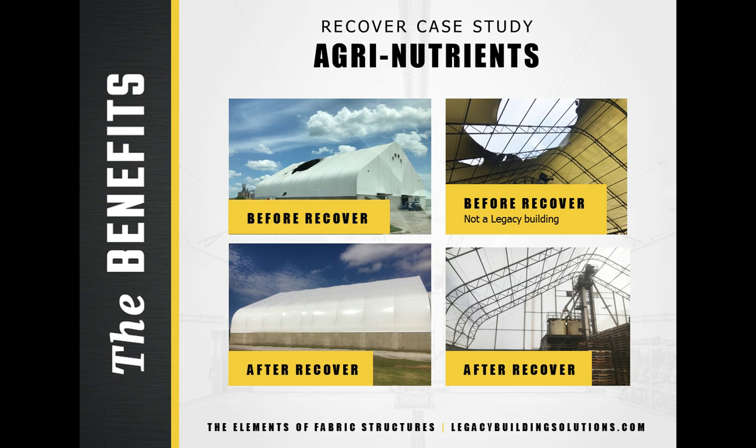As shown in the picture above, a fabric building is self-ventilating. In the presence of heat or fire, the PVC will melt away from the flame rather than feeding it. Often, most of the damage from a fire is caused by excessive heat buildup within the building. In a fire event, the fabric melts away, allowing the heat to escape and drastically reducing the damage to the building. The ventilation also provides an escape route for smoke, which is one of the most deadly elements of a fire. The fire that occurred in the building shown above caused virtually no structural damage to the building, significantly reducing cost and downtime for its owner.